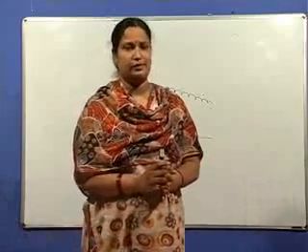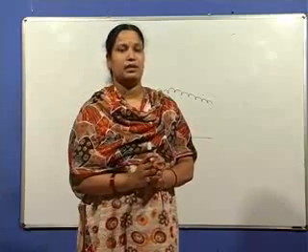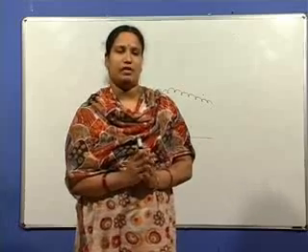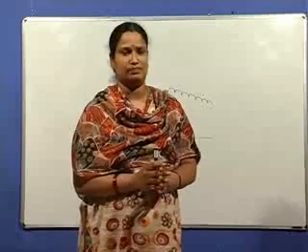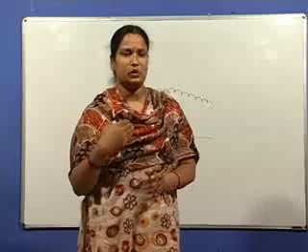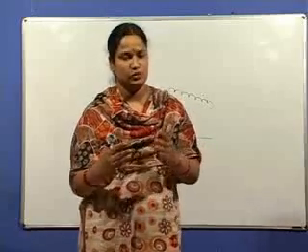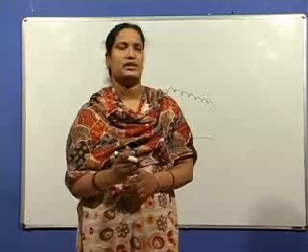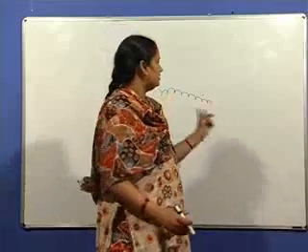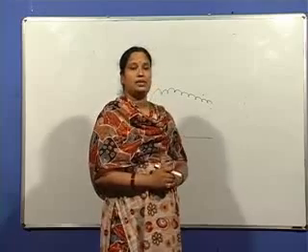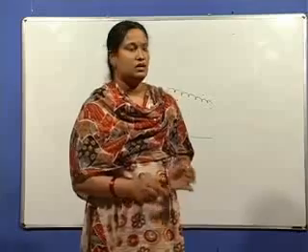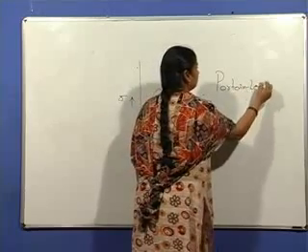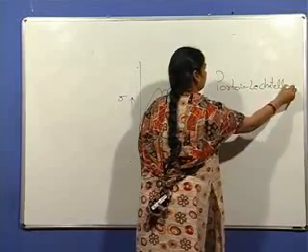And the dynamic strain aging behavior is seen at slightly higher temperatures but below 400 degrees centigrade. The main reason for this is that these solute atoms rapidly diffuse to the dislocation core and try to lock them. And again the dislocations try to overcome these obstacles, and again these solute atoms diffuse rapidly to pin down the dislocations. This continuous pinning and unpinning of the dislocations by the solute atoms gives rise to continuous fine serrations in the stress strain curve. This dynamic strain aging behavior is also related to an effect known as the Portevin-Le Chatelier effect.